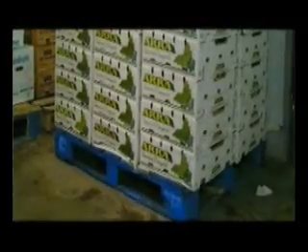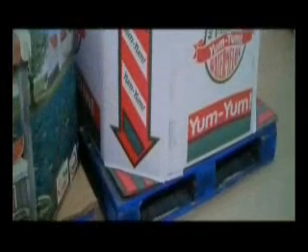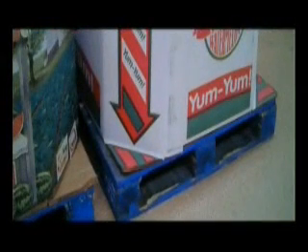But for wood packaging products that will carry food, pharmaceuticals, or other products that cannot be exposed to mold and stain, either surface drying or reducing overall moisture content to below 20% may be required. If drying is going to be required, then the system should be equipped with this capability.